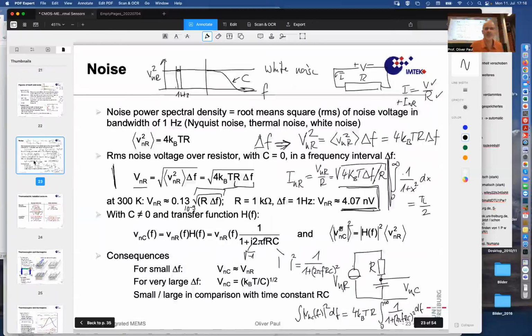Was that here? Yes. Here we had an electrical formula that said that if a capacitor is at temperature T, over all frequencies that are relevant, this capacitor will have a fluctuating noise voltage given by KBT over the electrical capacity of that capacitor with the square root.